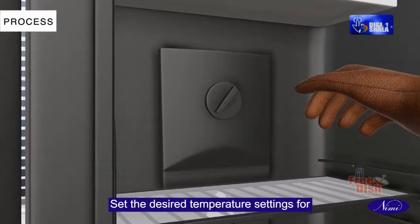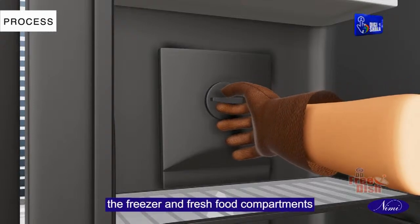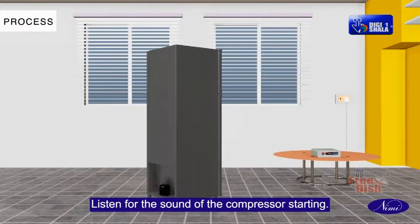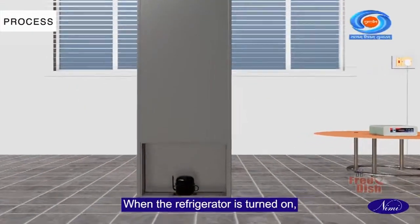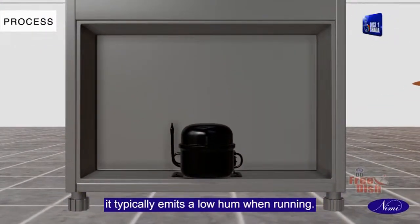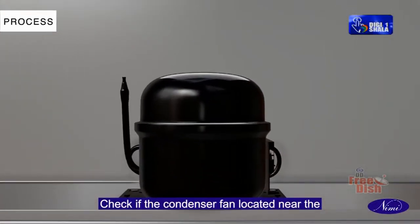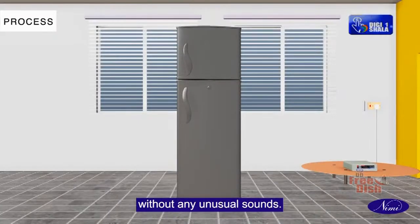Set the desired temperature settings for the freezer and fresh food compartments as per the refrigerator's manual recommendations. Listen for the sound of the compressor starting when the refrigerator is turned on. It typically emits a low hum when running. Check if the condenser fan located near the compressor is running smoothly without any unusual sounds.